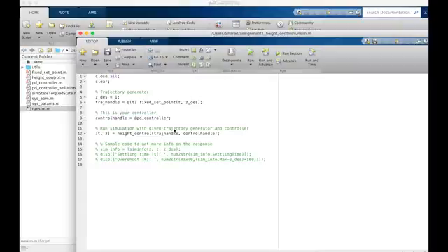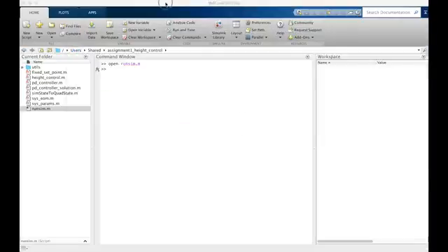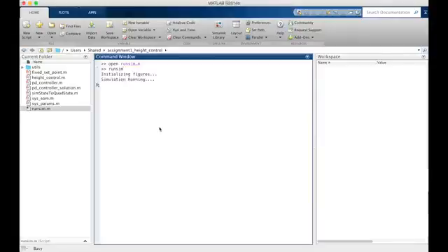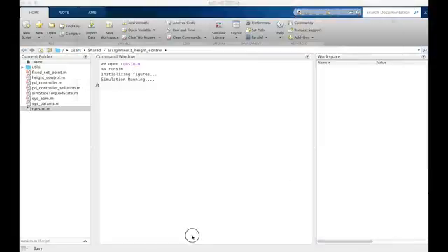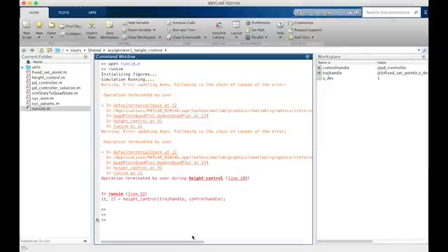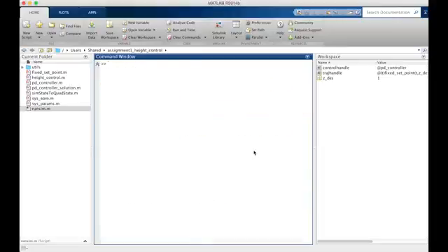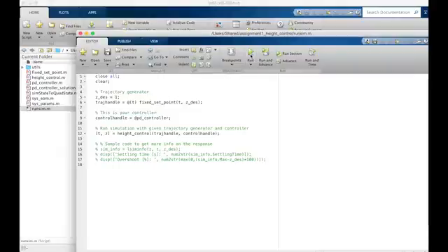To run this file, you can type in RunSim in the command window. You can prematurely exit execution of this file by pressing Ctrl-C. You can use the command clc to clear the command window. An alternate way to run the program is to click the green Run button in the editor.